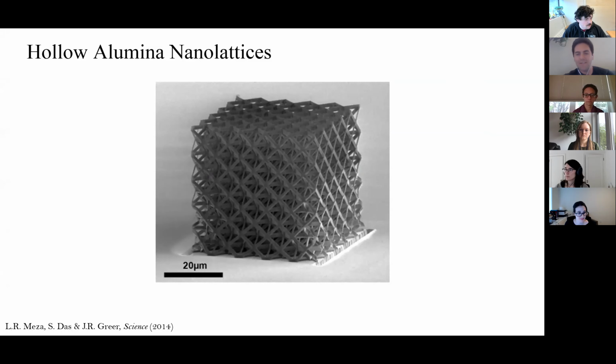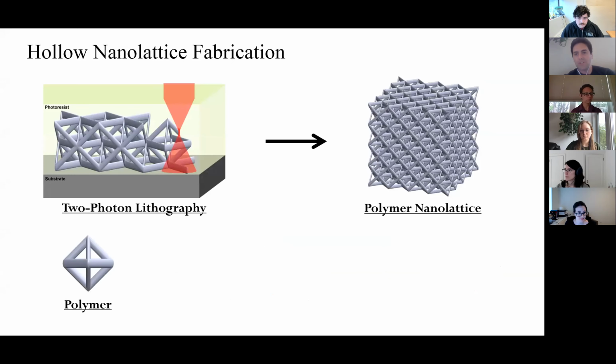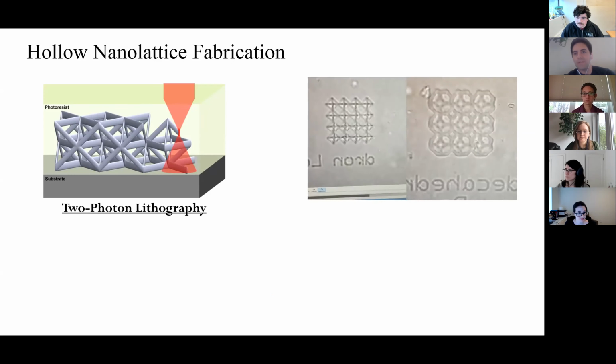Awesome. And then we have one last question. How do the properties of materials made by two-photon lithography compare to traditional 3D printing? Are there similar flaws like voids and cracks that you produce in the process? There are. So it depends on the writing method you're using. So I had shown you can do layer by layer or full 3D writing.